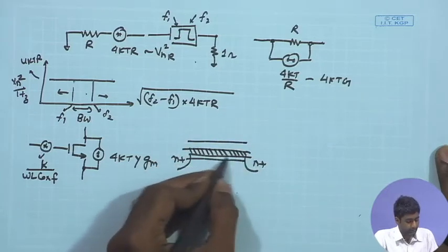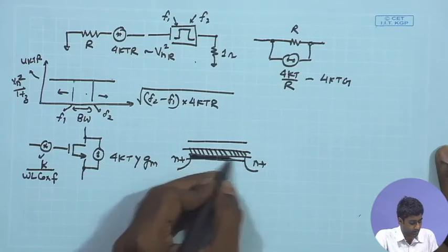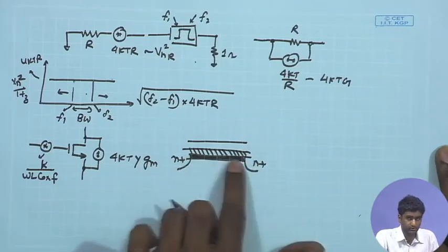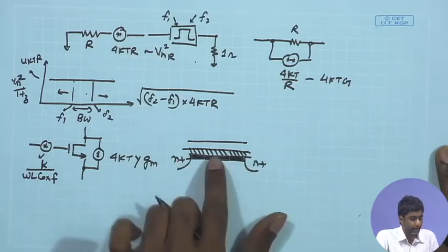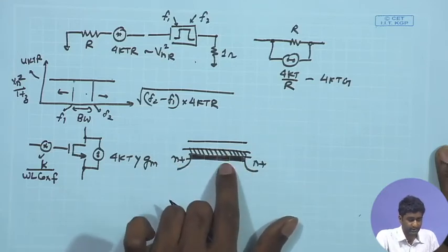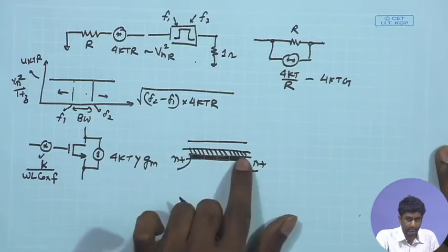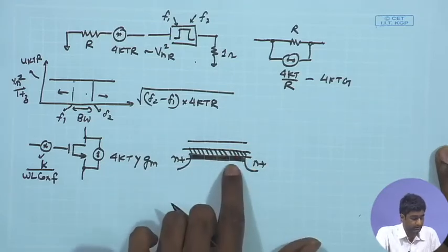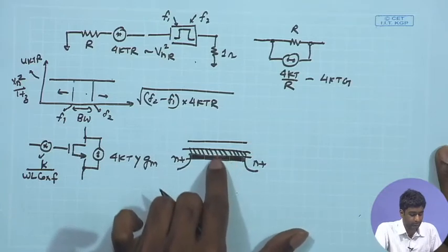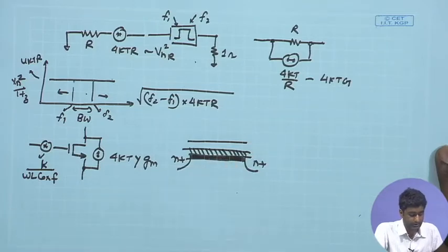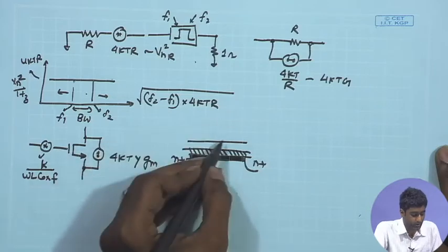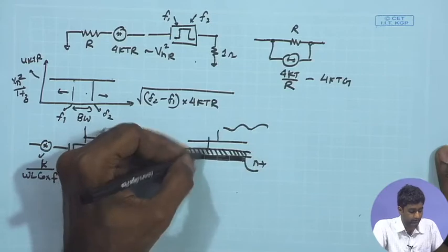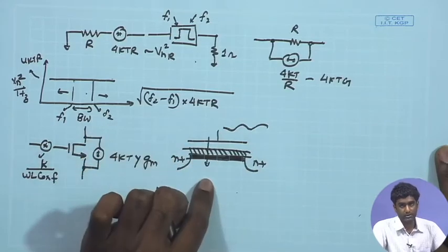So, you have this channel in an N MOSFET, which is denoted by this dark region, where you have a lot of electrons shooting from the drain to source, and the interface between the oxide and the channel is imperfect. It has dangling bonds where some of these electrons can get trapped. So, basically there is a continuous trapping of electrons going on at this interface. Moreover, you have a gate voltage which may be varying, you are applying some signal, because of which the electric field from the gate to the channel is also varying.